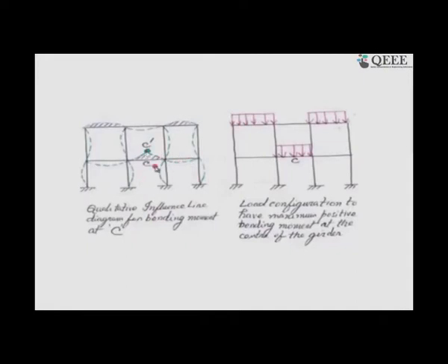If the internal hinge is formed, then I can say that this portion should go up, but since this is a statically indeterminate structure, this joint, which is a beam column junction which is stiff, will not give way, and it will try to maintain the 90 degrees with respect to the columns and the beams. So, because I have lifted this position, this is the bent portion of the girder. At the beam column junction, the whole thing needs to rotate, that is what it has done.